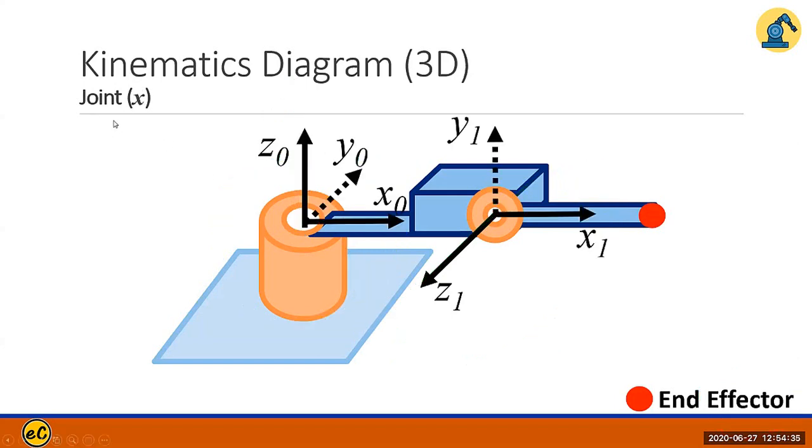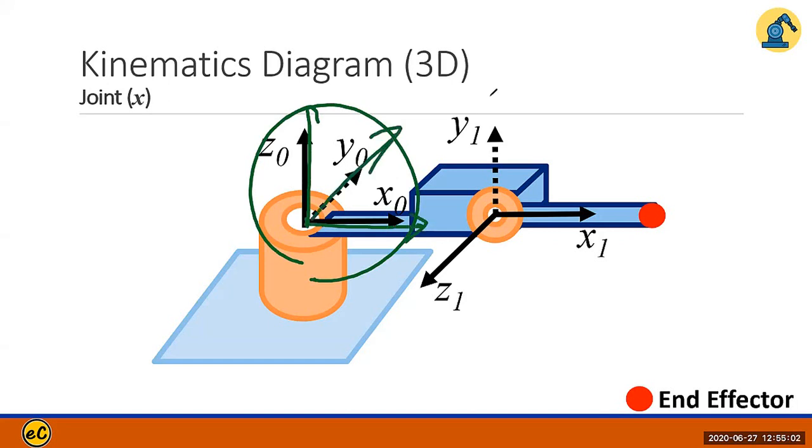Now, let's look at the X axis. At the revolute joint, we create a kinematic frame to describe the coordinates. So basically, at each point, we would have X, Y, Z, 3 axes. Right here, in this frame over here, we have Z in this direction, which we have already decided. And then X in this direction, Y in this direction. Y is into the paper. So here we have Z out of the paper, X in this direction, and Y in this direction.